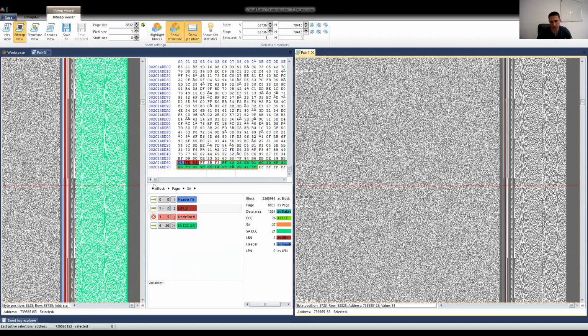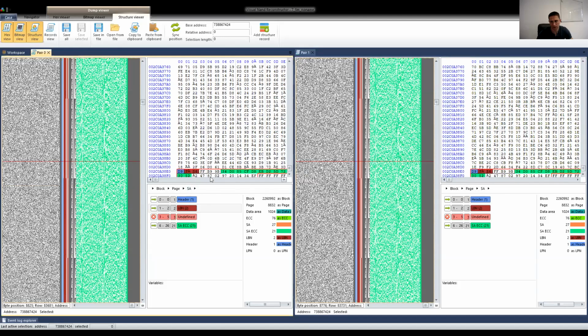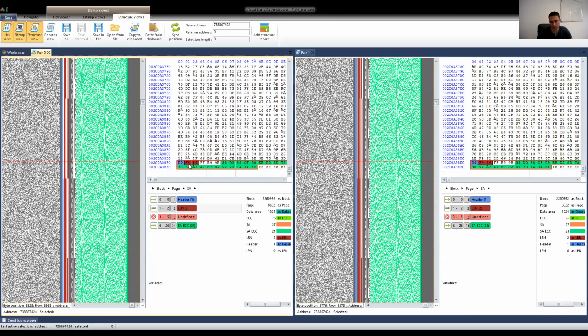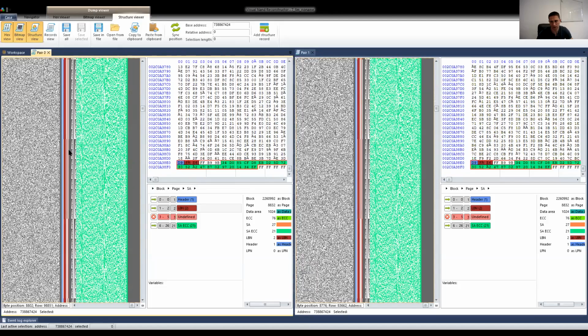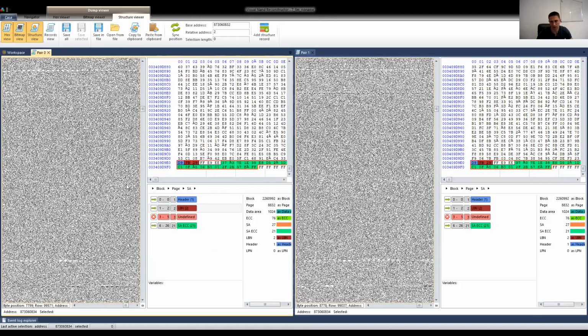Now let's do the same for the second element. So hex view, structure view, service area. And again, I click here and it will automatically jump. And have a look, FA56, FA56. So LBN is the same. Means that one block was written into both chips, both crystals, FB29, FB29. So this just proves my suspicion that I should unite these two dumps by pairs, or sorry, by pages.